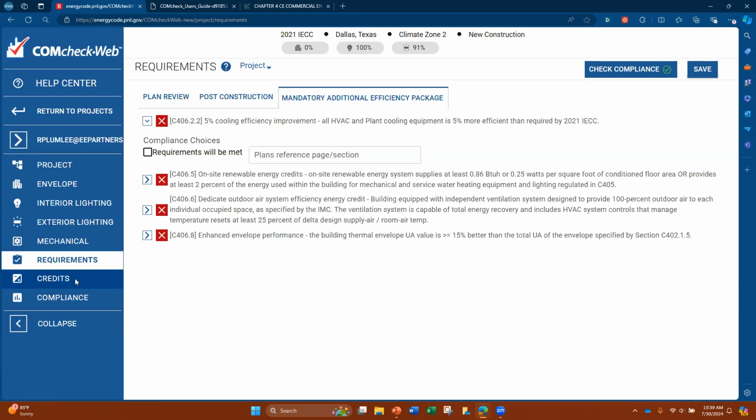It's not that easy when you get to commercial, because most of the time commercial buildings will not be using a blower door to verify your air barrier. It's easy to do on residential, because now we can test it and say, you have a threshold to get to, and it has to be that or better. Once I run the blower door, if it comes in at 3 ACH, then you must have done something right.